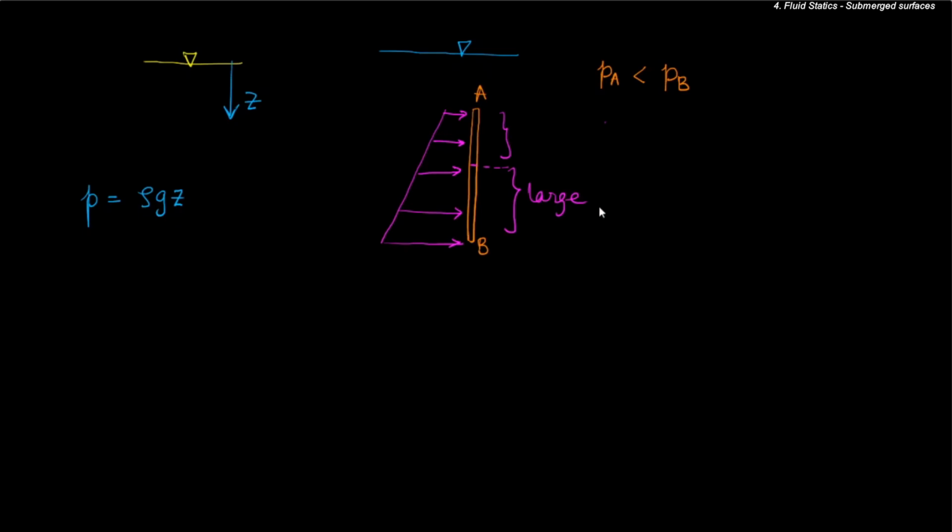So in that case, we can sort of imagine that the neutral axis, or the point where the effective force is said to act, can lie somewhere over here. It is not going to be at the centroid. When can the force be acting at the centroid? When the pressure is uniform. If this is the kind of pressure distribution by whatever means, then yes, we can say that the net pressure acts through this point.